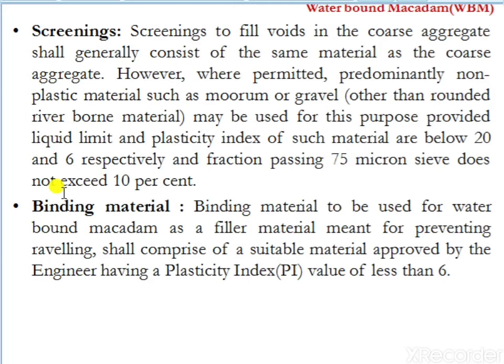However, where permitted, predominantly non-plastic materials such as moorum or gravels other than rounded riverborne materials may be used for this purpose, provided the liquid limit and plasticity index of such materials are below 20 and 6% respectively, and the fraction passing 75 micron sieve does not exceed 10%.